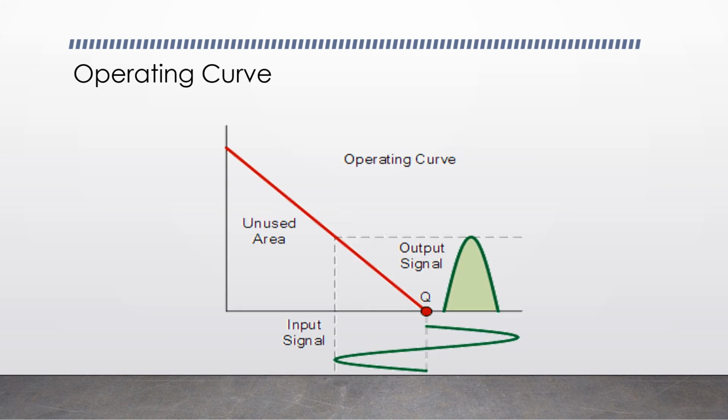So let us see the operating curve. In each transistor, only one conducts through one half, or 180 degrees. But as the output stage has a device for both halves of the signal waveform, the two halves are combined to produce a full linear output waveform.